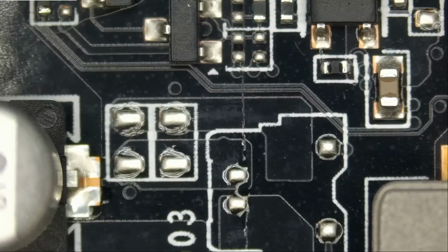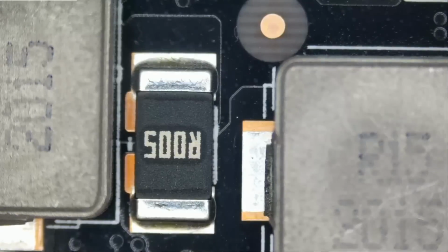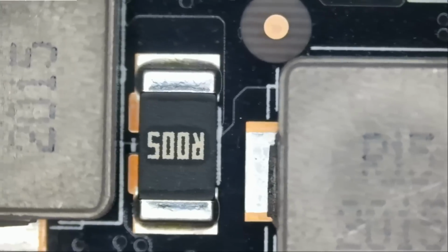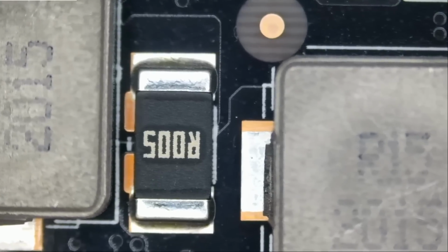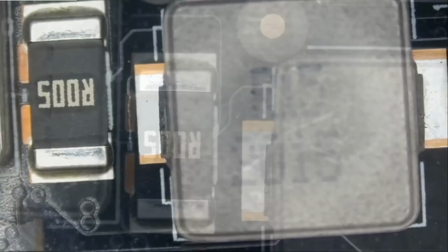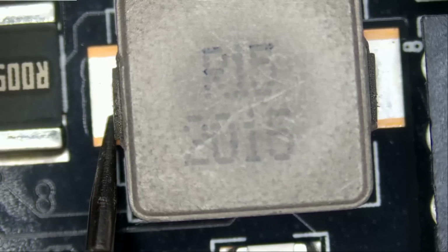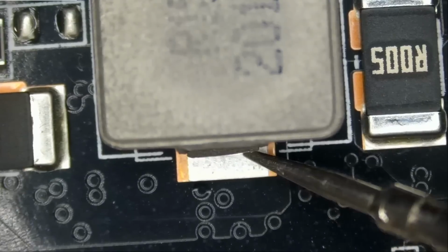So we're going to start by measuring the 12-volt rails, the coils here, that connect with the power connectors. We have 12 volts here, and we have 12 volts here. So I just want to quickly measure and see if we have a short on those coils, because if we do, it does not make sense to measure anything else on the board before we take care of those. Measure here, and we have 0.4 voltage drop. That's good. And measure here.